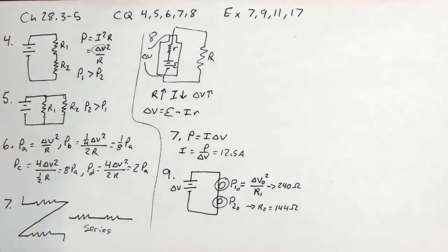Now the first question, qualitatively, semi-quantitatively, is just which one draws more power, the 60 watt or the 100 watt? Again, you might want to say, well, obviously the 100 watt, it's bigger wattage. But remember, that is the wattage assuming they both have the 120 volts across them. But they don't. There's 120 volts across the pair of them, but that's split between the two.